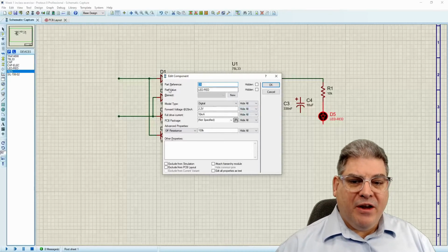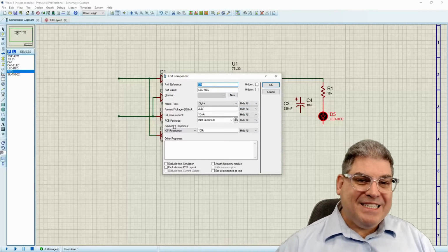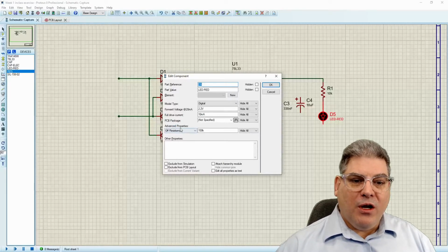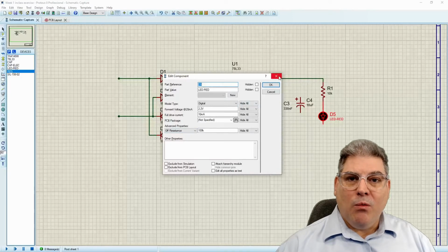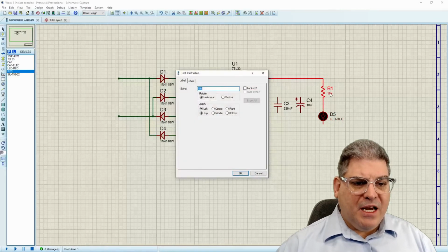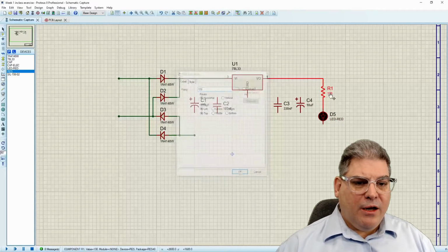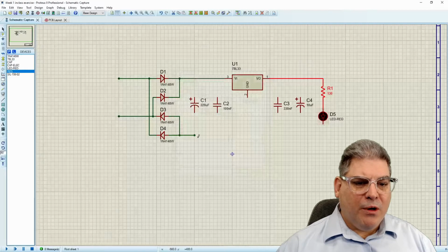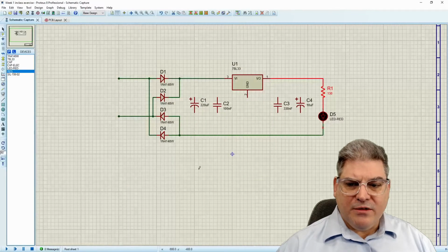But seeing as we're designing a 3.3 volt system today, you would use Ohm's law to calculate the resistor required for 10 milliamps at 1.1 volts or less. So in this case, I happen to give us a value, and I think 130 should be about right. So we'll connect this as we go across.